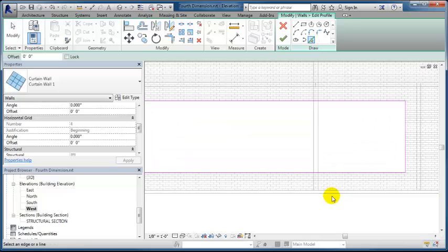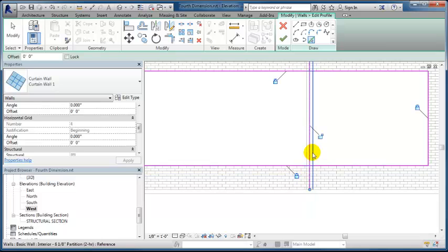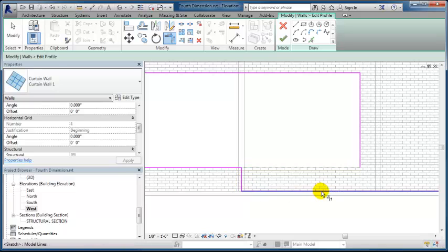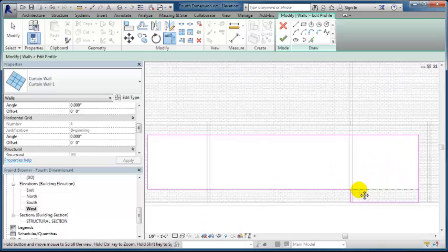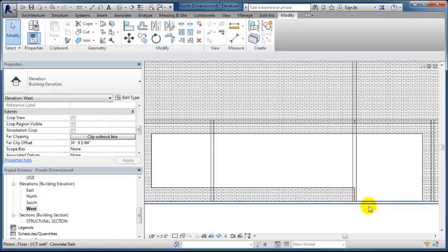And I'm going to go to the center of the wall at first. I want to add a section that comes down here, and I want it to come down to the floor. Then I can use the trim tool to trim that new shape of our curtain wall so it includes an opening right down to the floor here, which will allow us to install a door system with panels. So I'm going to hit the checkbox, and our new curtain wall goes right down to the floor.